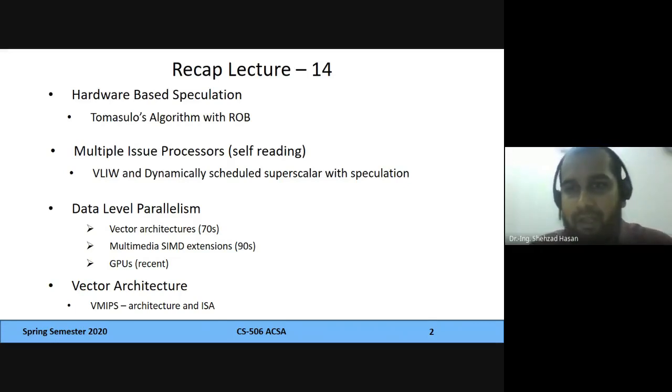The idea behind data level parallelism is that you want to execute a single instruction on multiple data items. Because that's a single instruction, you just have to generate the control signal once, and there are going to be multiple functional units which carry on their work simultaneously in parallel. So this speeds up everything because you do more than one task. It is a single instruction, but it is a big instruction. It has many operations inside it. So you do one task which has many operations, and this always speeds up the process.